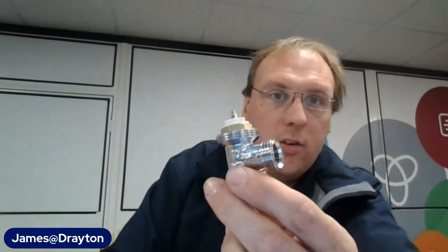With the 212 body, the only way you do your balancing is with your lock shield. So that's a key reason why, if the customer's considering a 212, have a look at the RT414 because it gets you the EB body. It also now gets you, or there is an option to have it with this, which is our latest body, which is the auto balancing body.